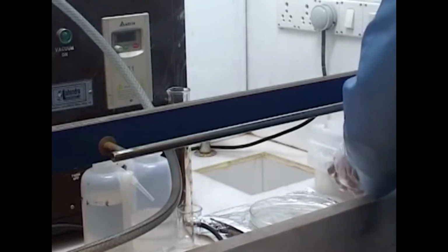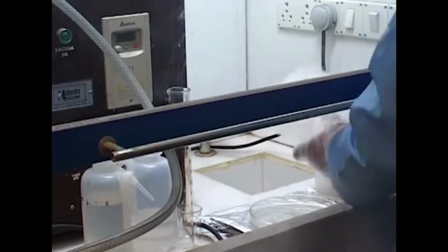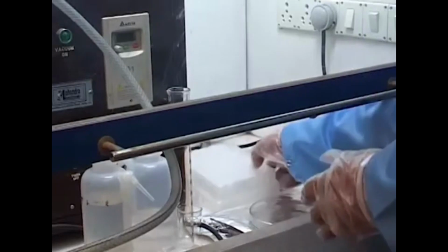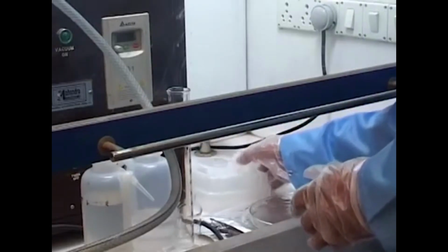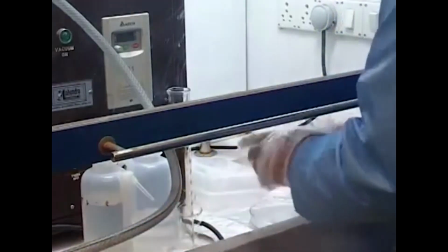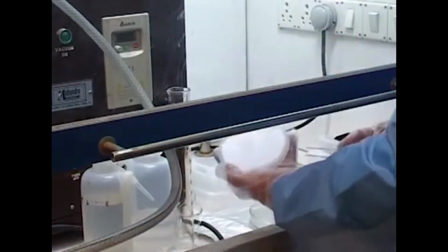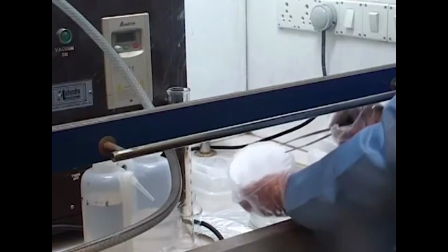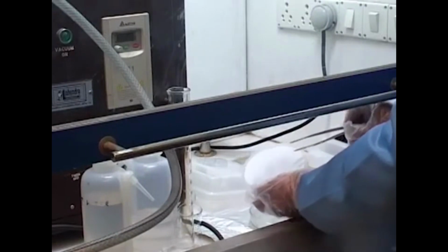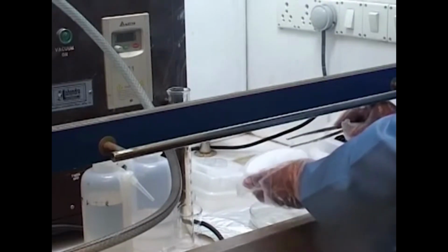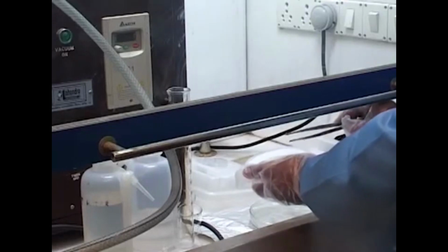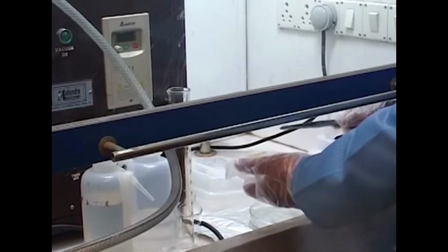So the first thing I am going to do is to unload a wafer from its box and take a separate container or wafer box and transfer this wafer. As you are seeing here, this really is a wafer box which is meant for containing a single wafer. For microfabrication, it is very important that, especially when the wafer is moving between workstations, we cover the wafer adequately so that you do not have any contamination as the workpiece is moving between stations.